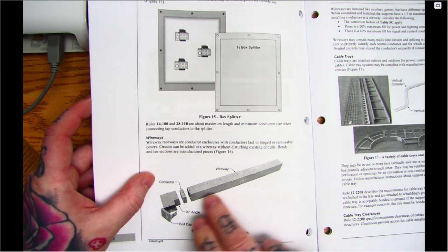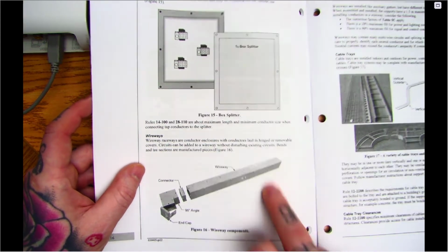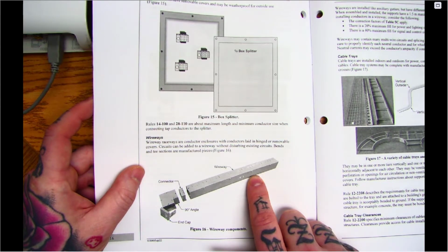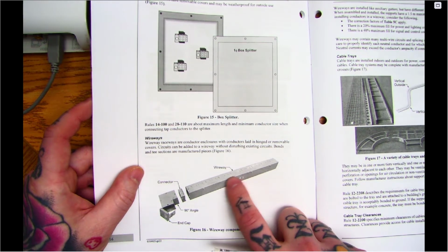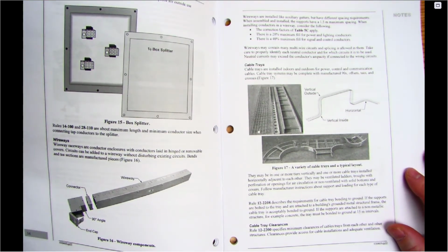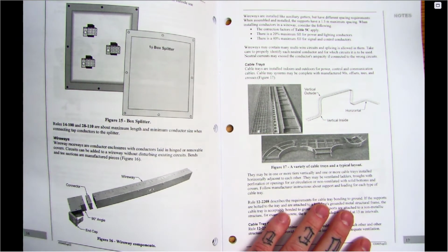I'm sure I've seen wireways. I worked in Saputo here in Red Deer, and they had a ton of stuff. And wireway, probably not the best location, because after what seemed to be decades, there was something dripping on it and eating away at it. So again, we, as electricians, if we're not always having prints to go off of, we got to make sure we understand what type of environment we're installing this in, and then the limitations of our equipment too. Okay.